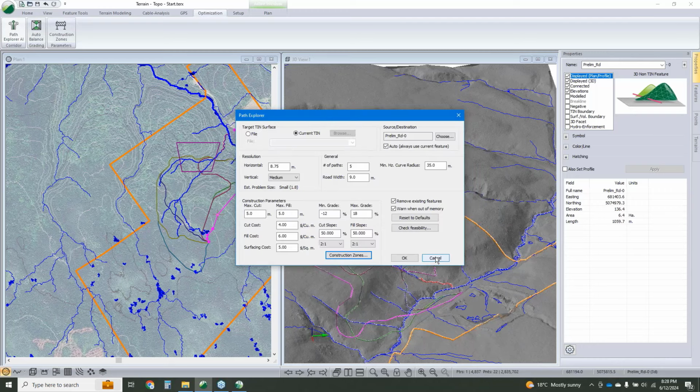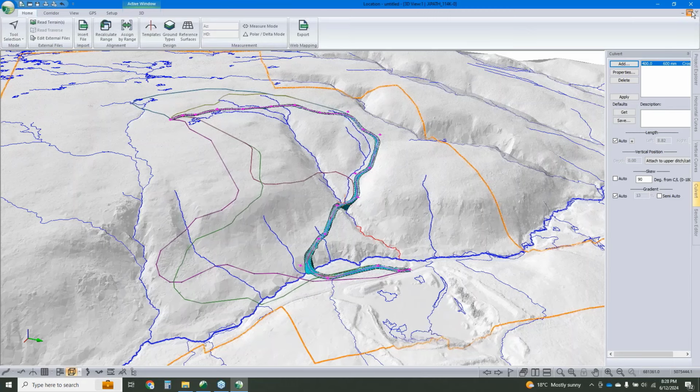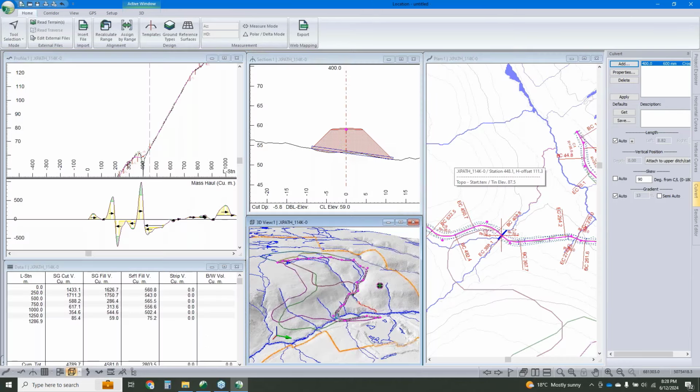The other side of that would be when you're doing your vertical optimization, if you are going through an area like that, you could make it so that the excavated material that comes out of there is not suitable for fill anywhere along your alignment, and you could designate that to go to a spoil site for treatment, or have that material only assigned through a specific range and keep it outside of, well, spreading the contaminant outside of its natural area.